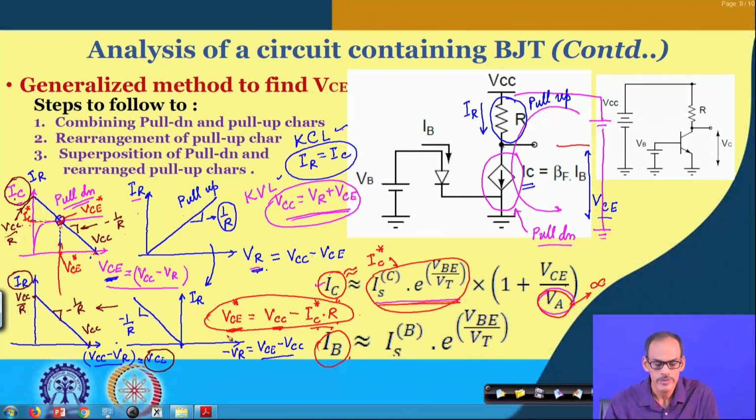Let us see what may be the variance in case we have a resistor in the bias circuit at the base. So, let us consider the corresponding example where we can put a resistor here, and instead of calling this VB, we can use a different notation. Let us call it VBB, and this is RB. Of course, that voltage is not directly giving the voltage at this point. So, we require an additional procedure to find the corresponding IB current, because VBB is not giving us the VB voltage.